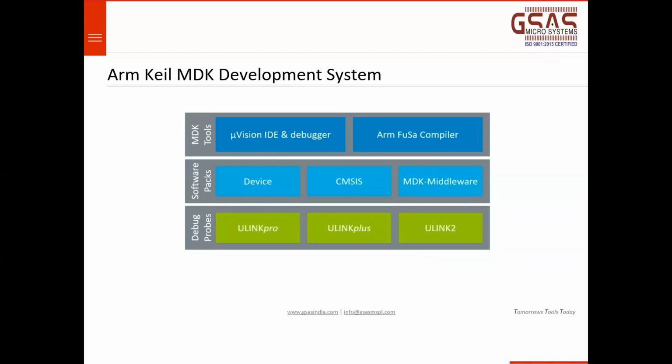Next, coming to MDK middleware. Everyone is aware of what middleware is. If not, I'll quickly tell what a middleware is. A middleware is one which sits between the application running on your hardware and the operating system. Suppose you have a hardware board on which you have ported an operating system, it can be Linux, Android, or even a normal FreeRTOS or any microcontroller RTOS. This middleware sits between your application and the OS, basically.